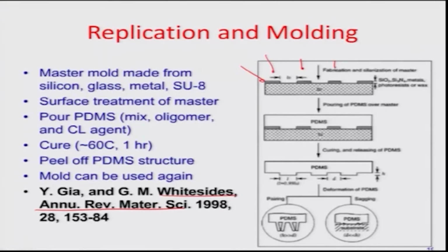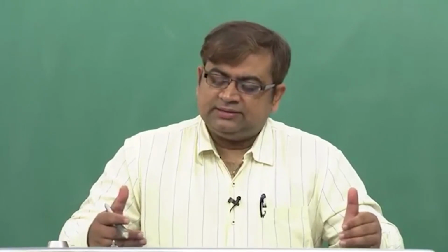Such a pattern is taken and silanized on its surface. So there is a thin molecular layer of a material which makes this surface highly hydrophobic in nature. You can think of it like the talc powder used in casting processes, which is used for separating the cast from the remaining portion of the mold. I had done this while talking about the first generation casting strategies in the earlier modules on manufacturing process technology part 1.